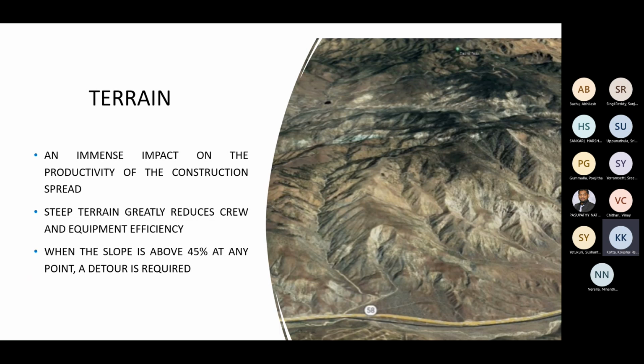If the construction is on an inclining plane or any declining slope, then the construction takes longer than expected, and the CO2 emissions will be more from the equipment we're going to use in the construction. Normally the maximum slope we consider is 0 to 15%. That's an ordinary slope, but we shouldn't consider routing in a construction where the slope is over 45%.